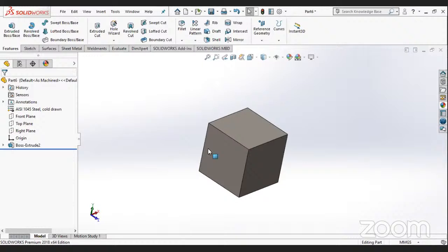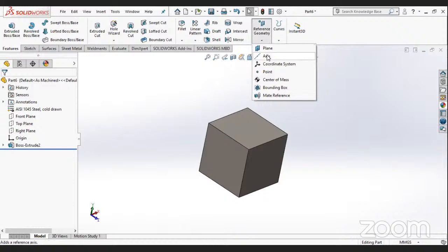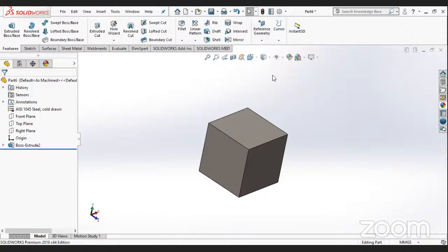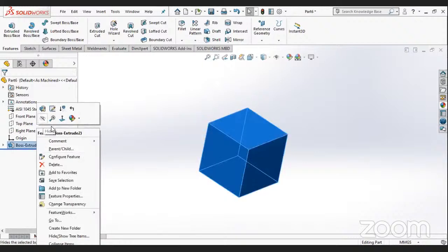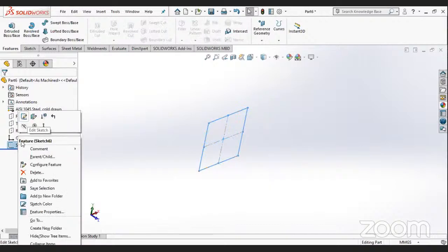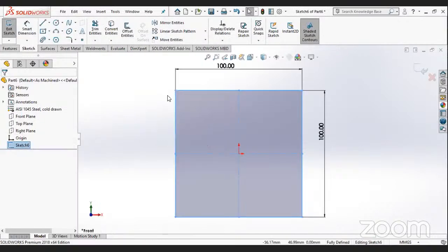After this, I'll tell you some features from your 3D model features. In here, you can see that you can also take axis, meaning a reference axis, which I told you, which you can also take from here, hides and unhides. For that, I'll have to make a shaft to show you how the axis works. So I'll quickly delete this and make a circular shaft.